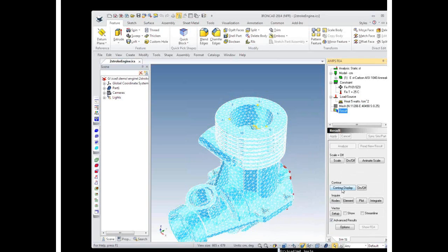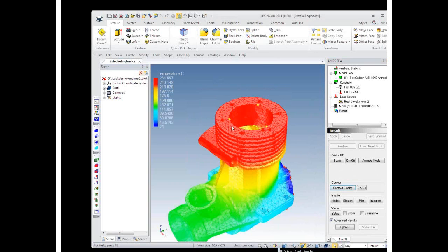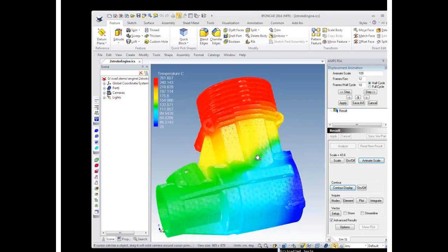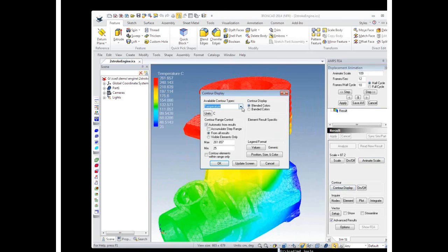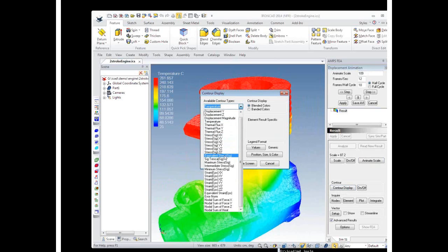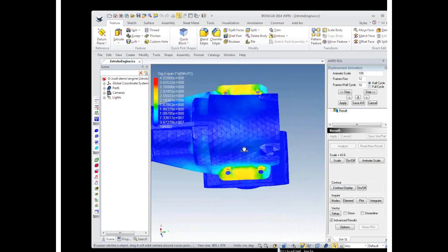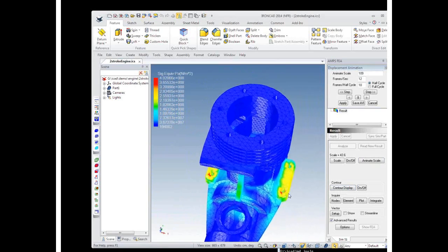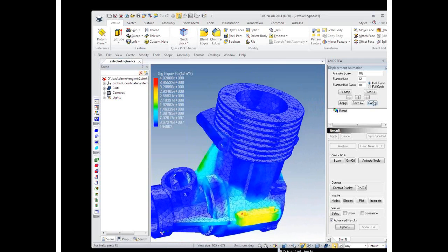So if you analyze this one, you can see due to the combustion behavior, you will have a temperature that is rising very quickly. And if you look at the coupled motion of the stress and thermal, this is the behavior, okay? And you can look at also the stress, which is basically crucial in this design, equivalent stress. So that's equivalent stress because it's supporting it here. This is a hookup to the front of the airplane. So this is the part that you want to be careful when you bolt it to the wood, okay? So not much, but it's things that when you're designing parts, that's the thing that you're looking for.